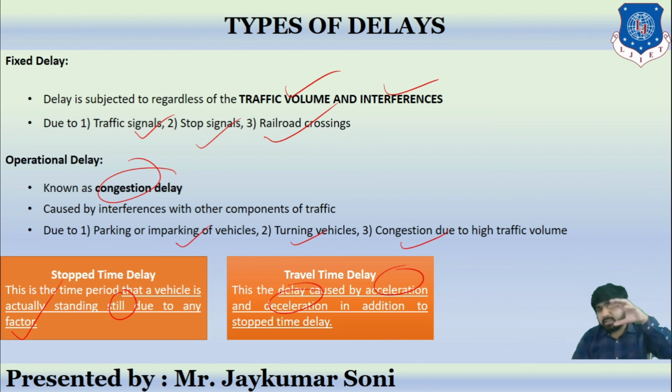If the vehicle is standing, that is stop time delay. If you are traveling on the road and due to traffic you are accelerating and then slowing down your speed, that is also causing delay. That is called travel time delay. So this is all about travel time and delay studies.